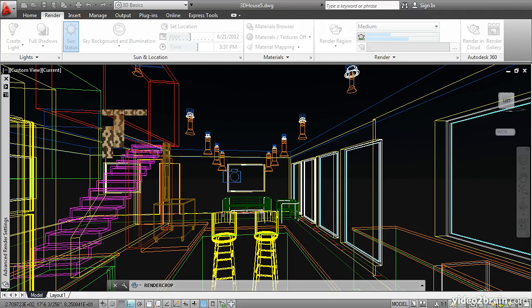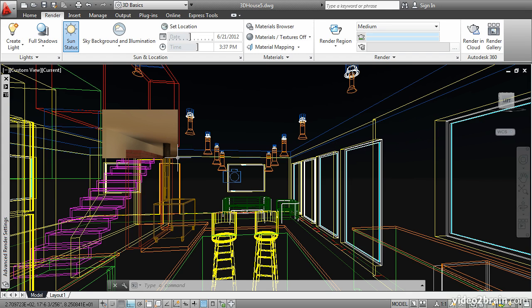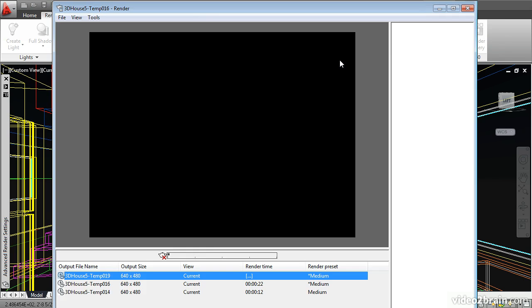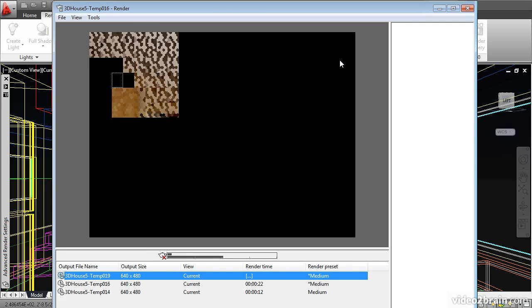The Final Gather results are starting to come in, and at first they're very blocky. The way it works is it progressively refines the results. The squares get smaller and smaller until eventually we'll have a nice continuous gradation of light. That's starting to look good. Okay, I think we're ready to make a final render. Go up to the teapot icon, open its flyout, and choose Render. This will take some time as the results come in.